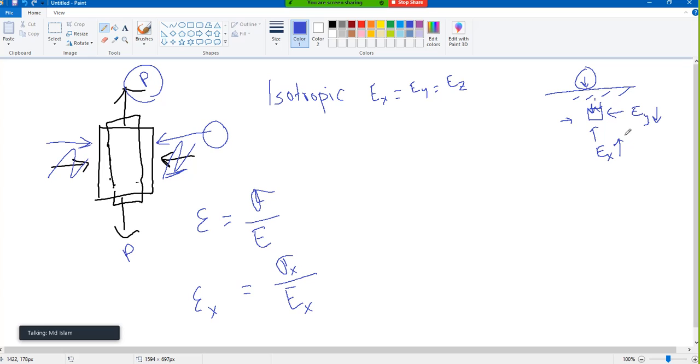But in concrete, even when you compact, in concrete we vibrate. As we vibrate, we can assume that it is getting compacted in all directions the same way. So in concrete we use this. So that is the meaning of isotropic. In undergraduate we always assume isotropic. So I will not write Ex. E. Any direction, E.